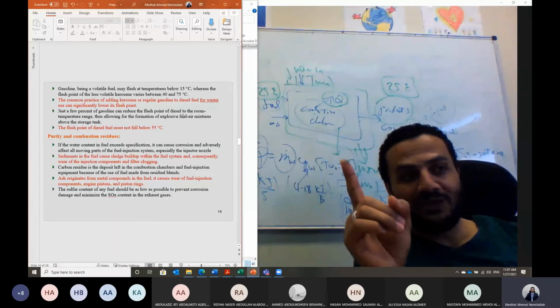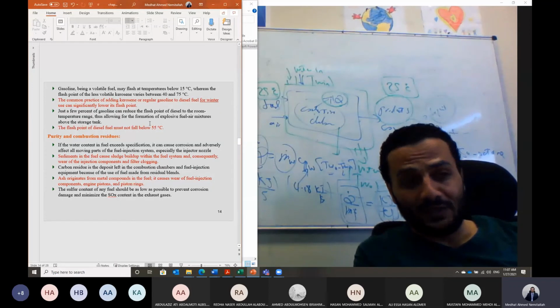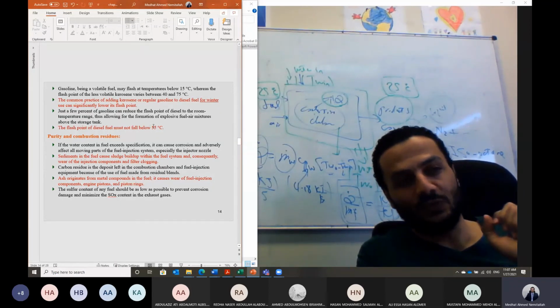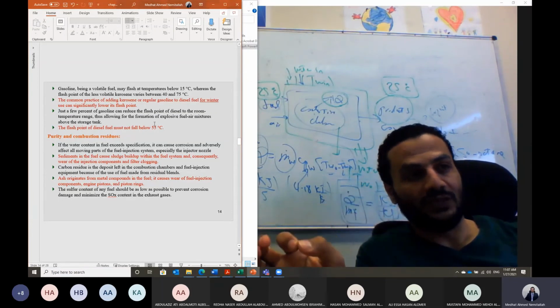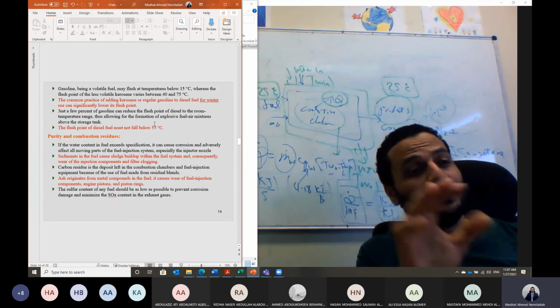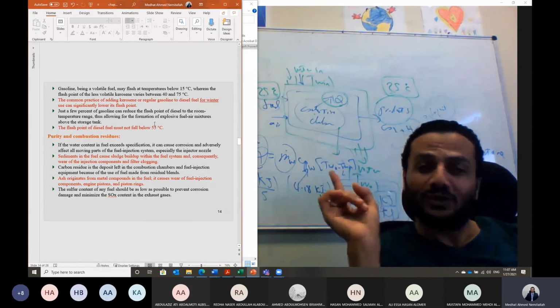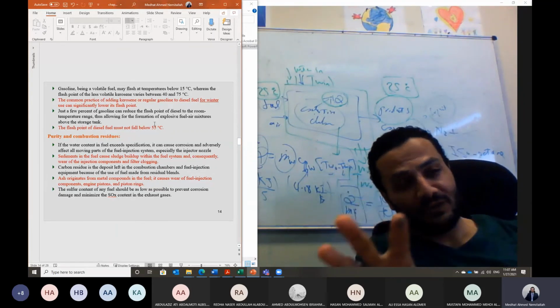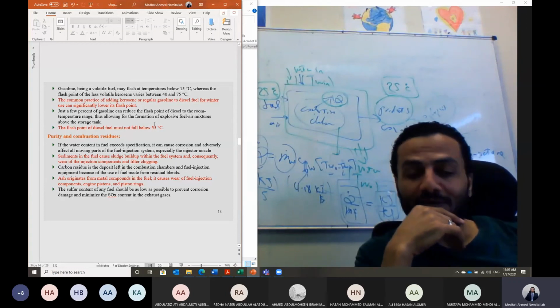But please, Shabab, don't do this, because adding gasoline or kerosene, even a small fraction, will result in a large reduction in the flash point temperature. And this may result in an explosion of your fuel tank. So don't do this. They are already doing this for you at the gasoline station. This is for the very cold winter, not even in Saudi Arabia, okay? Because here, mashallah, the weather is doing well.